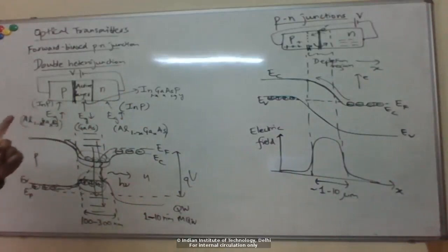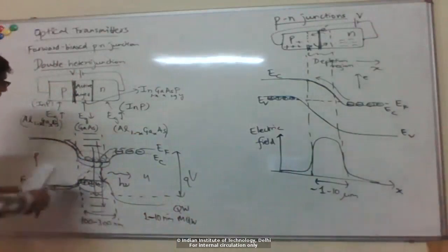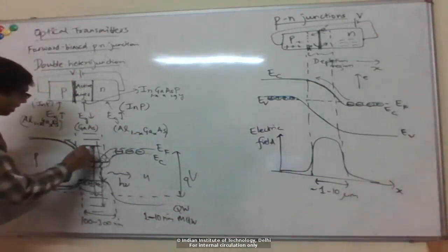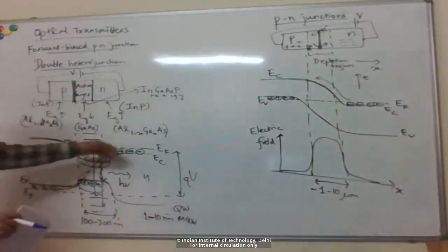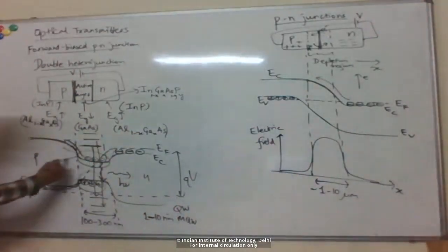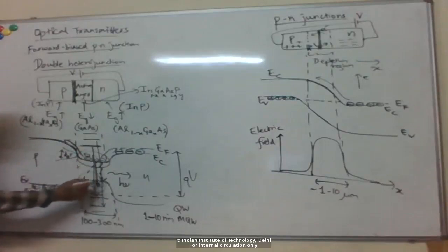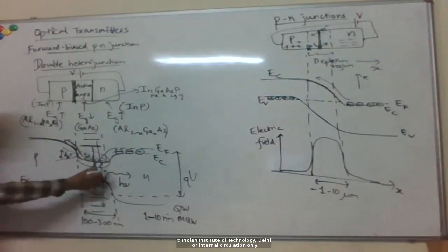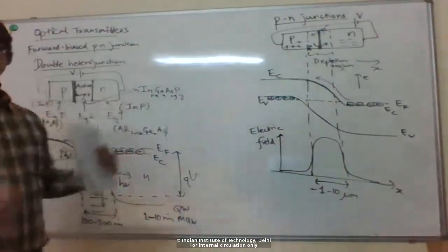But if you want truly single frequency with ultra narrow line width, like below megahertz or something, then one way to do that is, for example, to make this kind of quantum well structure where you have a discrete energy level. So that's a very well defined energy level here. Recall that for the semiconductor, there was some spread in the energies here, which is roughly kT. So when they recombine, you can imagine that the emitted photon has a spread in energies, right? So that gives you a spectral width.